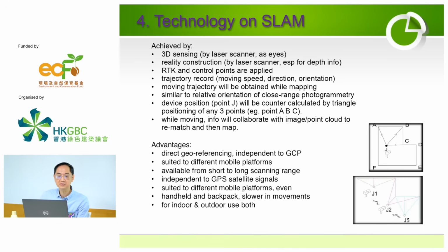Handheld is the best performing for surveying. The poorest one is the UAV, of course, because the UAV is vibrating or moving in the air. So if we can, we do handheld, but most of the time we cannot, because we need to do building surveys. So we have no choice but to use the UAV with SLAM technology. It is also very suitable for indoor if you use the handheld. Later on we will have a case study to show you.